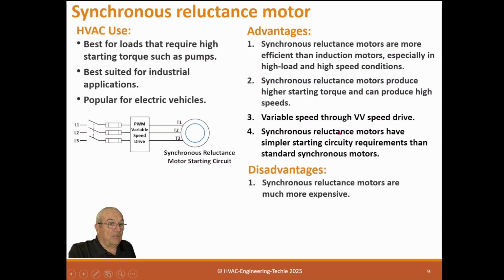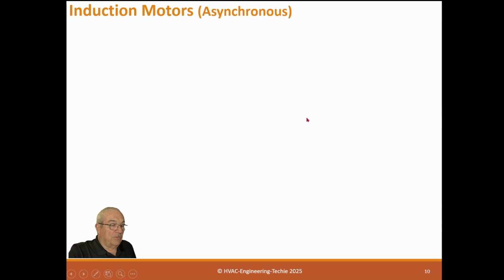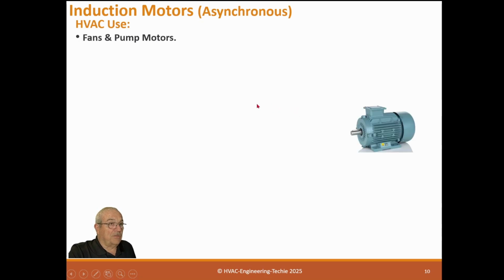Disadvantage is that reluctance motors are much more expensive. Requires a matched variable speed drive. No big deal, but that's what they are. So you will start seeing some synchronous reluctance motors on projects because they are now being sold in the industry. Induction motors, that's asynchronous.